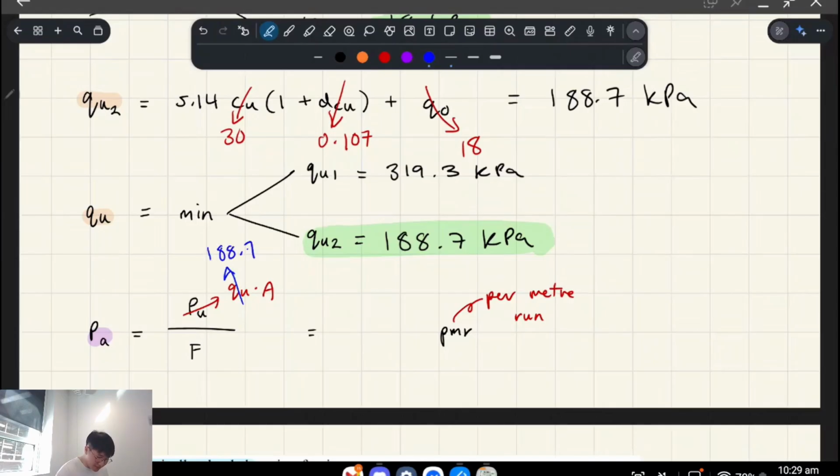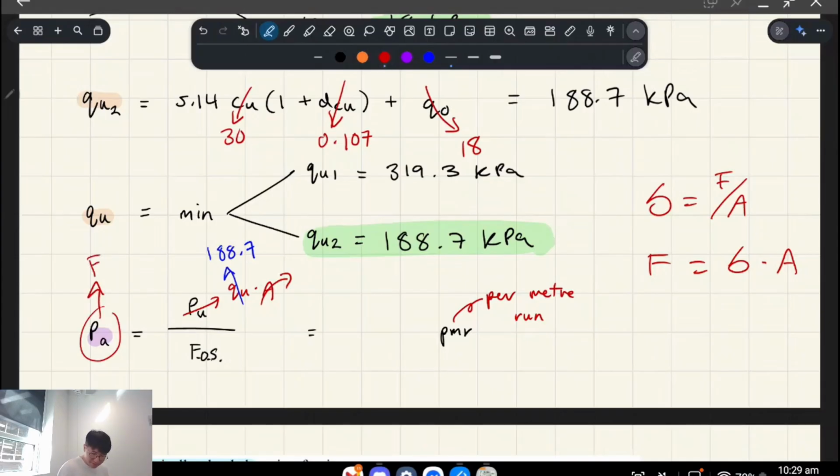So this formula is telling us what is the max allowable force, basically, right? So stress is force over area, and force is stress times area, right? So this is our force. Let's call that this factor of safety, FOS. So this is the equivalent of F, right, in this equation, and this is our stress, right? The max stress that it can take, and area is 1.5, okay?